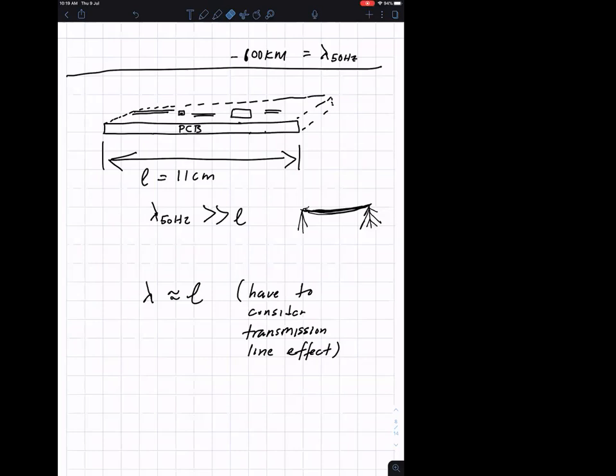But there's another thing, like what you guys mentioned here, the EMF and everything. It can cause capacitive coupling. This is your road, this is the car potential, right? And because it's high voltage, there's always a capacitor. This capacitor can discharge on anyone at any time. One guy died last time when it was raining and he was standing under the power line doing something.